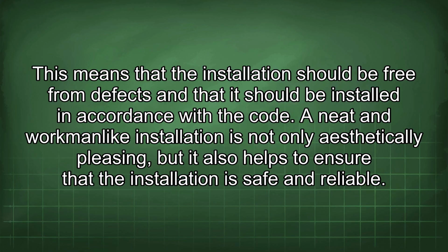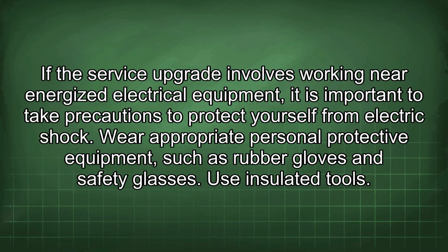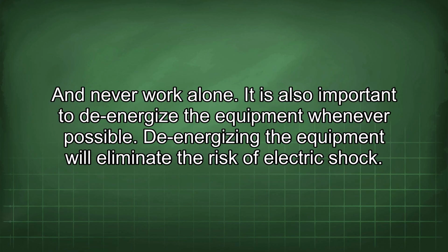If the service upgrade involves working near energized electrical equipment, it is important to take precautions to protect yourself from electric shock. Wear appropriate personal protective equipment, such as rubber gloves and safety glasses. Use insulated tools. And never work alone.